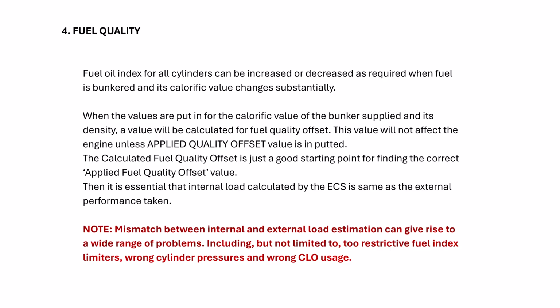Remember, the calculated fuel quality offset is just a good starting point for finding the correct applied fuel quality offset. So use the calculated fuel quality offset as the starting value. Now you see what value it is calculating, and take performance and compare. Then you can make the necessary adjustment. Make sure what you have taken in performance and what it is showing is the same. Then you don't have to do anything until you consume this bunker.